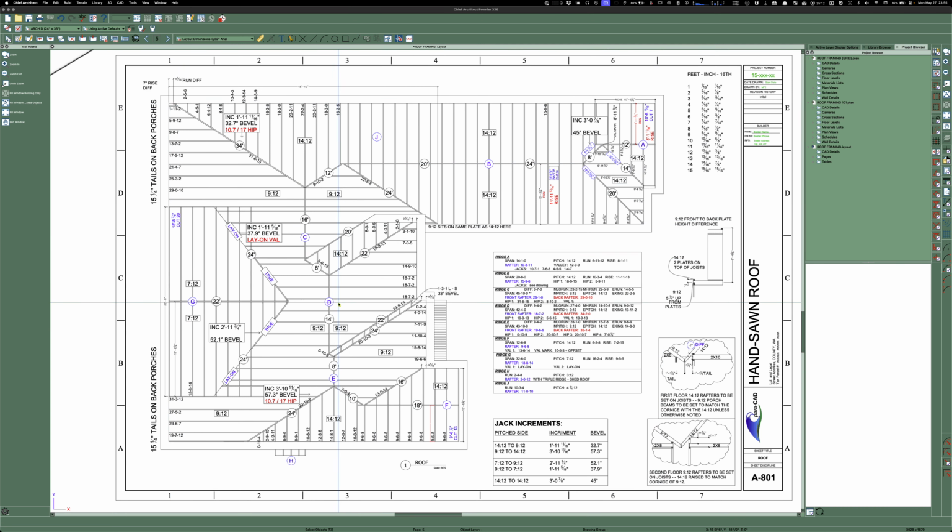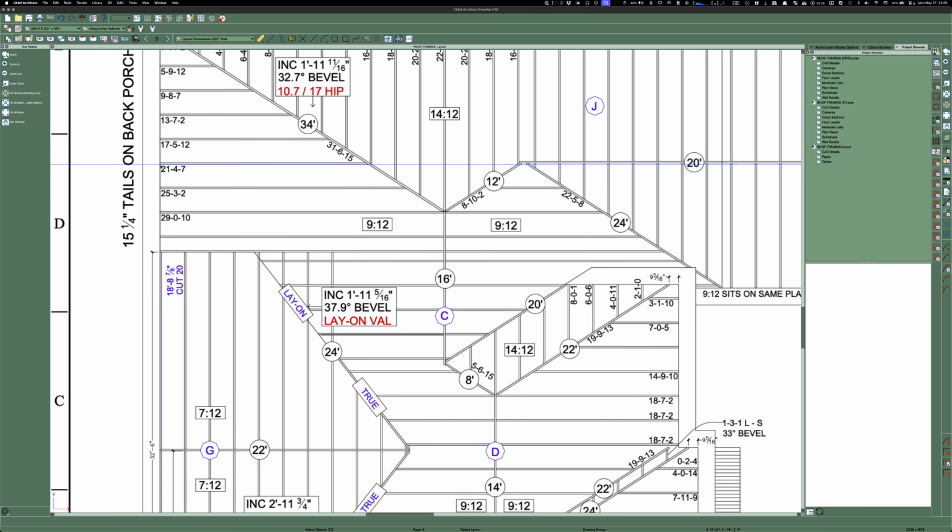And in the South on slabs, they shoot the plate down or they hit it with cut nails. And so you've got your bottom plate already where it's supposed to be. And we just made sure everything was in the right location. And then since it was right, I already had all this electronically, and so I just ran the calculations. Some of these tough things, like I would measure from right there to the long point horizontally, and then enter that information as the run, and then put a 9 and 12 pitch on it, and then it'll give me the length. This is the diagonal.